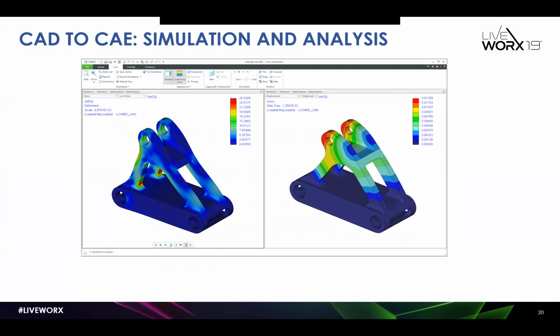The engineer developed a few design concepts and options. How did he choose which way to go? I showed him how to perform modal analyses in Creo Simulate, and he had his answer. Those quick, simple analyses told him which concept was stiffest and assured him that its natural frequencies weren't near the RPMs of our motors and blades. The modal analysis also provided quick feedback on how to strengthen and lighten the part.